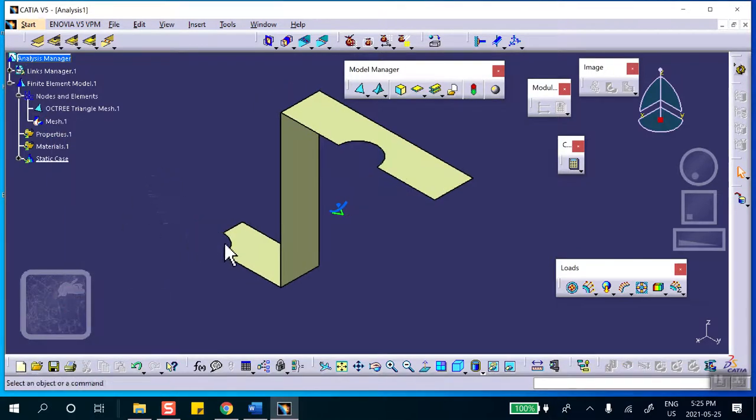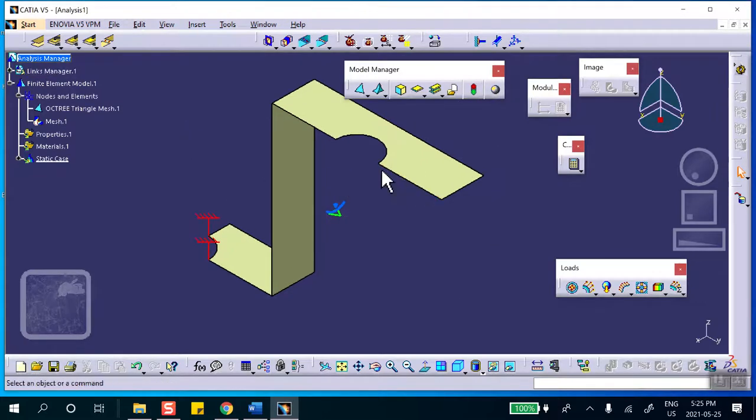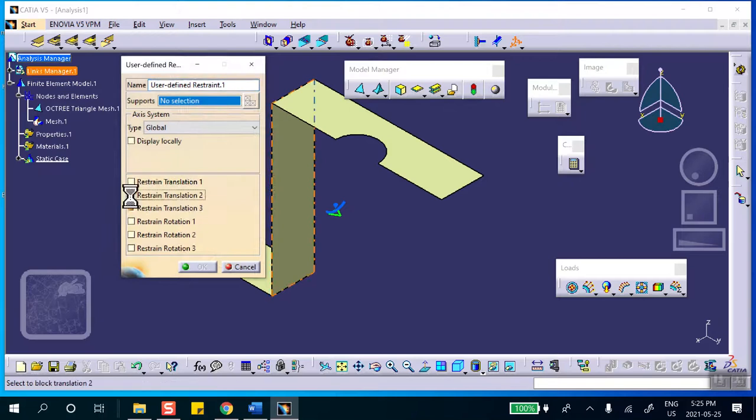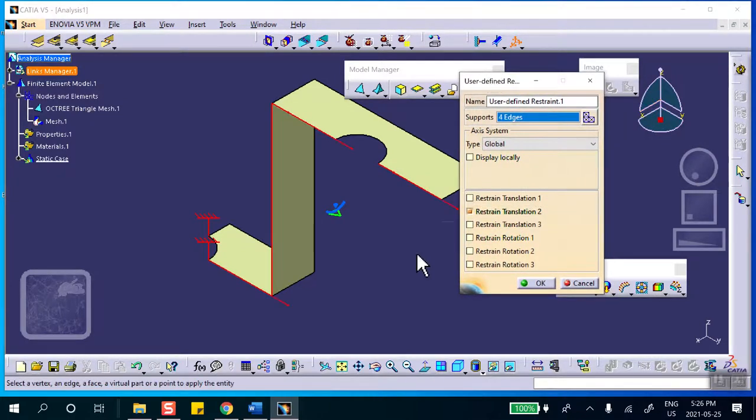Okay. So this bottom circle is clamped. And then these are planes of symmetry. So let's uncheck all of these. For edge control, I think you can select them one at a time. You don't need to use the control. So this and that, these four are planes of symmetry, and they lie in the XZ plane. So no displacement in Y.